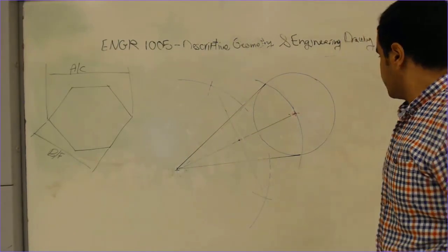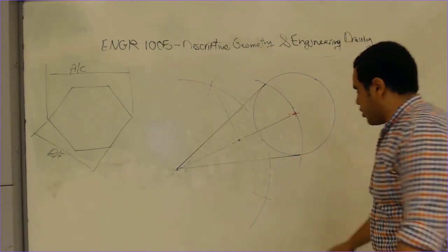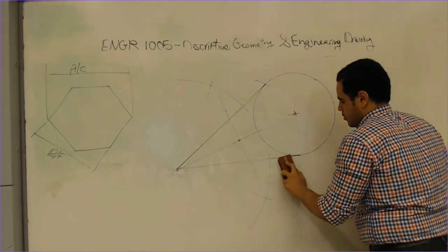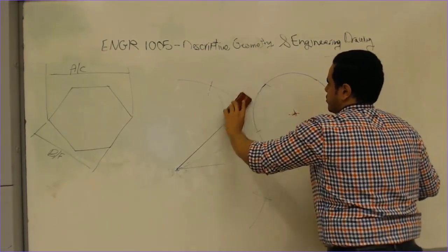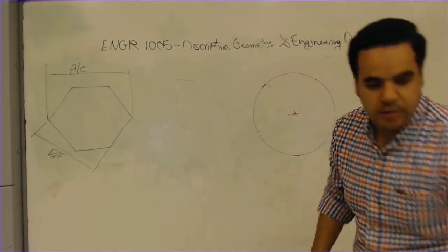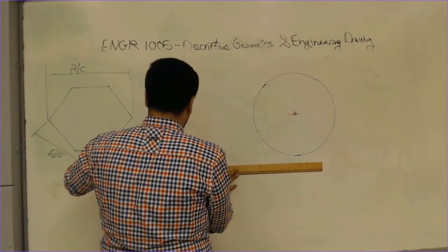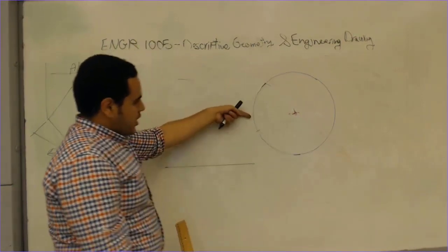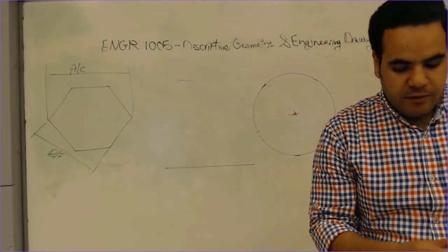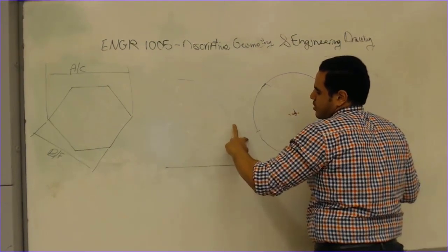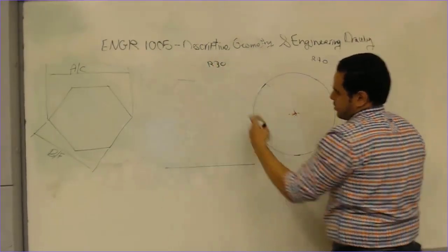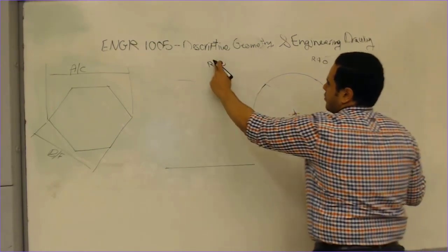Now, we said this circle is 40, so I'm going to keep this circle. I'm going to erase all this. Now, if you have a line like this, and you want to draw a tangent arc between this line and this circle. How to do this? First, it will be given that the radius of the arc, let's consider this is R40, and you want an R30 as a tangent to this circle, or R50, let's consider it R50,